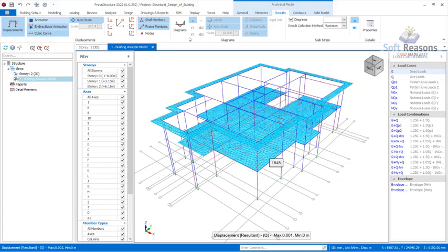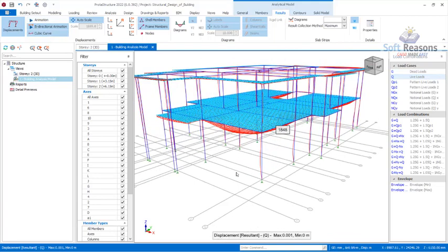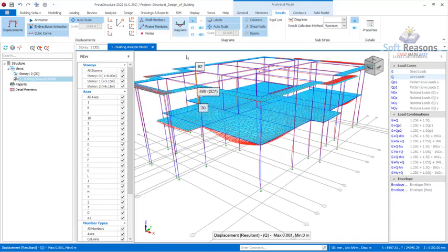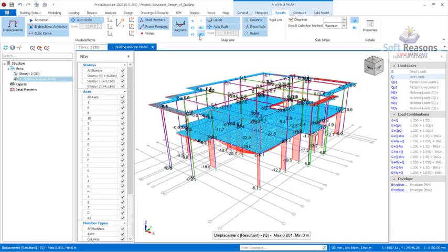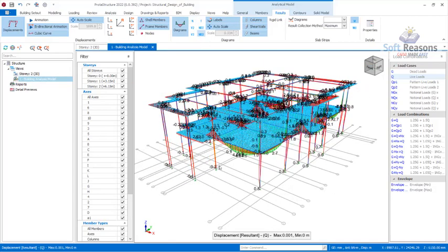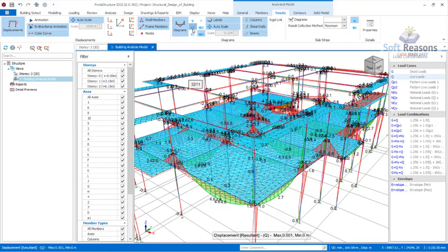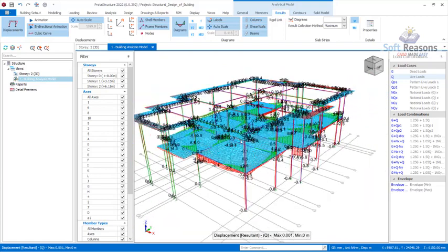Okay, and check that, and then to be able to view the deflections, the moments, by activating the diagrams. Okay, and then M3 is for the bending moment diagram. So M2, V2 is for shear force. So you can check all of that successfully.